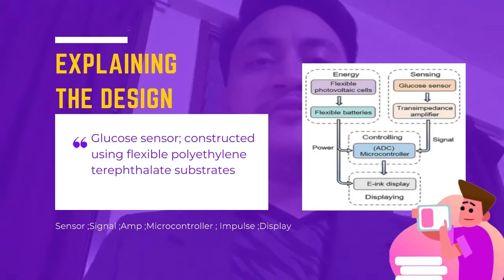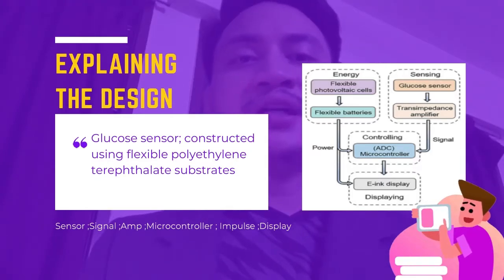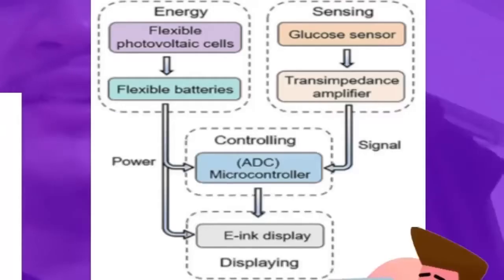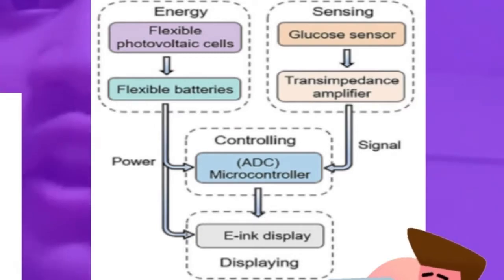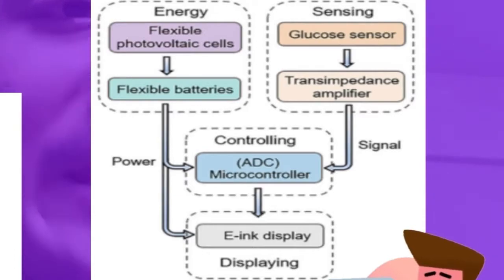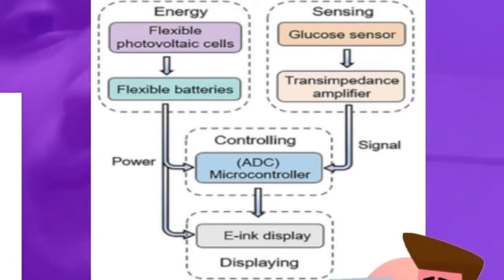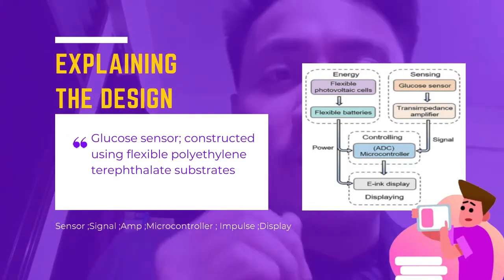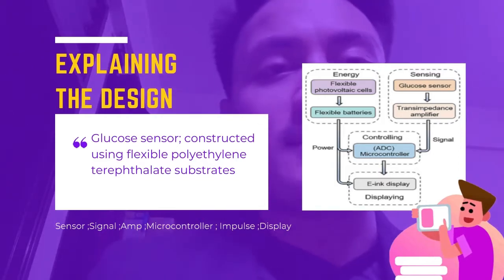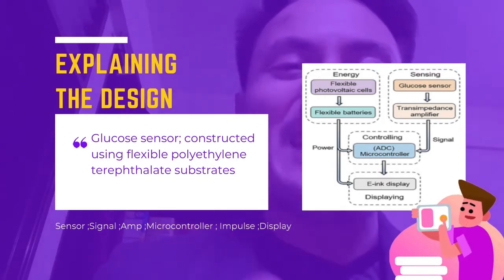The pre-programmed infinite impulse response filter will denoise the signal. The filtered signal is then used as a reference for the display. When a bootloader has been burned into the e-ink component, it is interfaced with the TinyDuino microcontroller via the serial peripheral interface and programmed via the universal serial bus, as shown in figure 3, which is the circuit diagram.